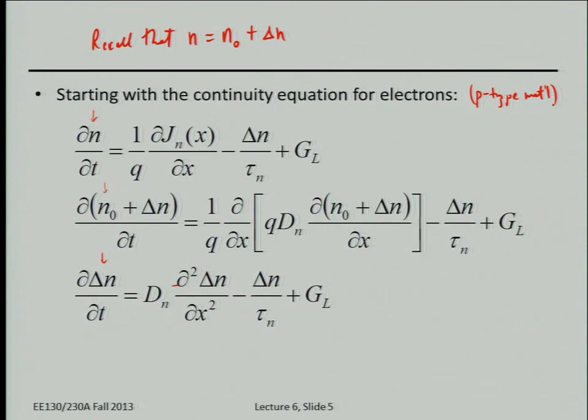That's right, the diffusion constant, right? So the diffusion constant, did he teach you the rhyme? D over mu is kT over q. He didn't, okay, so that's the Einstein relation. He derived it in class, right? So that's an easy way to remember. There's an Einstein relationship between the characteristic constant for drift and the characteristic constant for diffusion, and they're related. Hopefully, qualitatively, it makes sense. If an electron moves with higher mobility, then it should diffuse faster, right? So there's a relationship between D and mu. So D over mu is kT over q. That's really easy, hopefully, to remember.